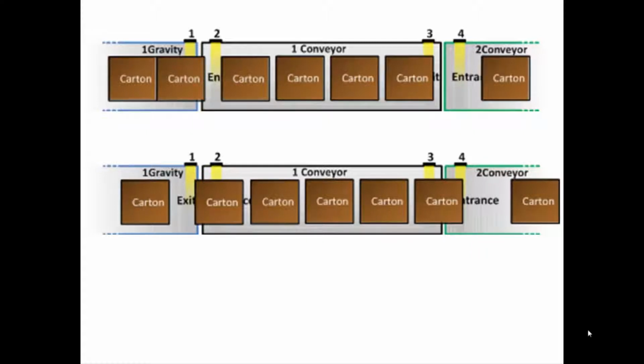We purposefully singulated the cartons on one conveyor by controlling the logic in such a way that one conveyor pulls one off at a speed faster than the next carton can fall by gravity. So the carton being pulled onto one conveyor just clears photo I2 and one conveyor stops before the carton can get down against the leading edge of one conveyor.